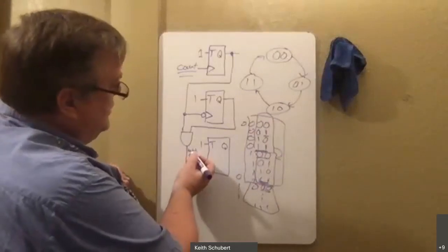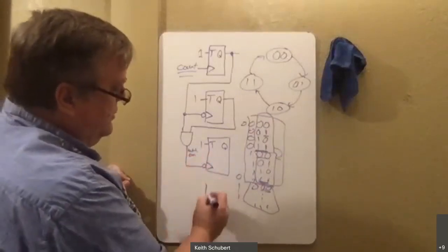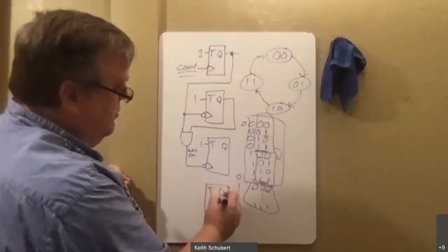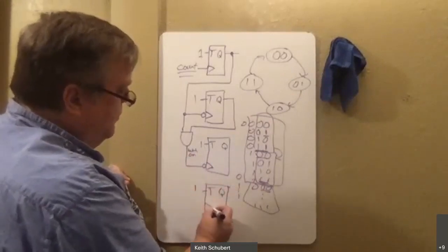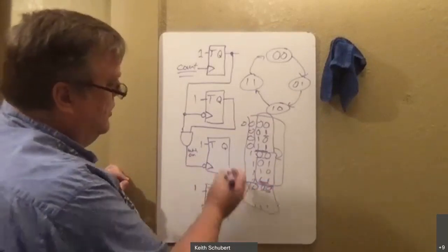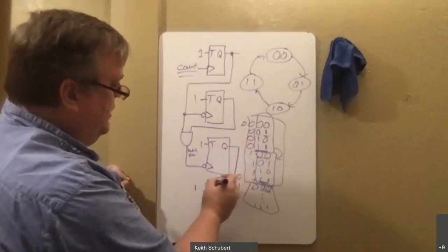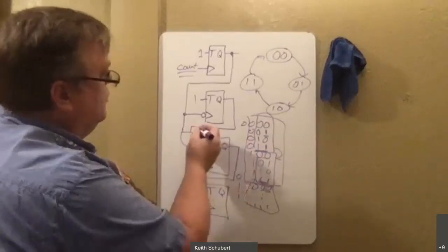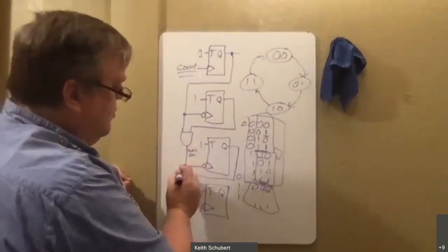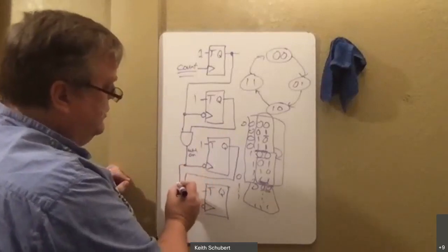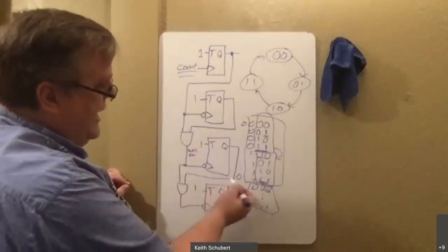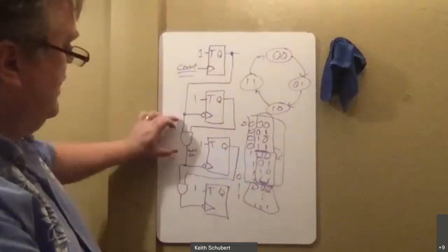Same thing. But when I build that next unit, and this is just the efficiency part that I wanted to mention to you, we notice it's still a toggle. For the clocking, it'll still be when it goes from 1s to 0s, so we have the inversion bubble. When I want to add this bit onto it, I don't need to pull both of these signals down. This AND already does both of those. So all I have to do is just tap the output of that AND gate, feed it into the next AND gate. And this just adds one more layer on. And so this same pattern repeats.